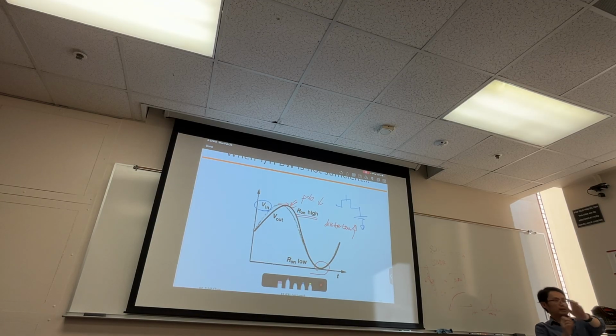So what kind of ADC spec will be worse? SNDR, SDR, SFDR, THD, and probably SFDR will go up, right? SNDR, how about SNDR? Okay, it will be worse, right? How about SNR? Same. Okay, so you guys are experts now.